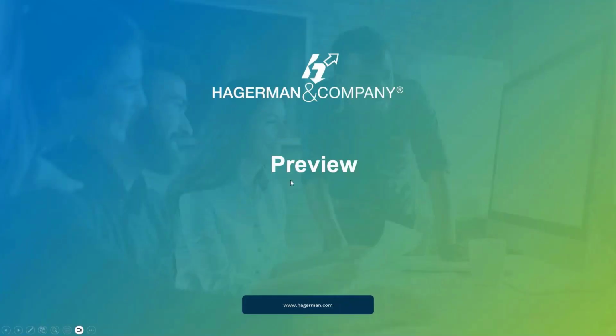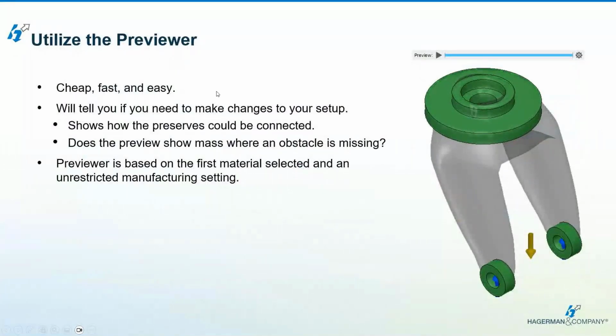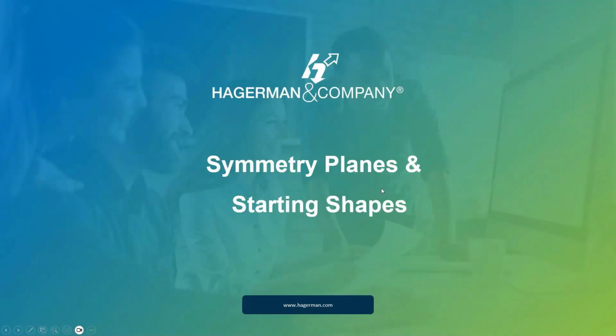As that's working, let's talk about that. So it's cheap, fast, and easy. Yeah, it's free to do. Once you need your finished designs, that's when it's going to take your tokens. And with this preview, I like using it too because it will let me know what we need to change and set up, what preserves we need, and if we need to place more obstacles in there so that it doesn't build and create the design inside of that. The previewer is just going to select the first material and that unrestricted manufacturing method, just to give you a quick view of that.